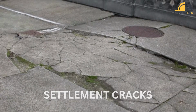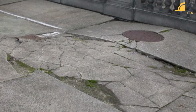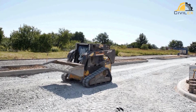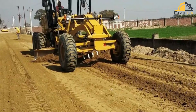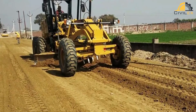Settlement cracks. These are cracks that occur when the soil beneath the concrete settles or shifts. Settlement cracks are often caused by inadequate preparation of the subgrade or by changes in the moisture content of the soil. To prevent settlement cracks, the subgrade should be properly prepared and compacted, and any changes in soil moisture levels should be monitored and addressed promptly.